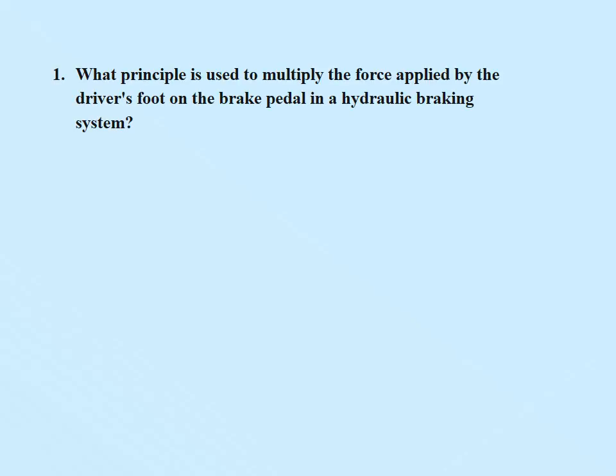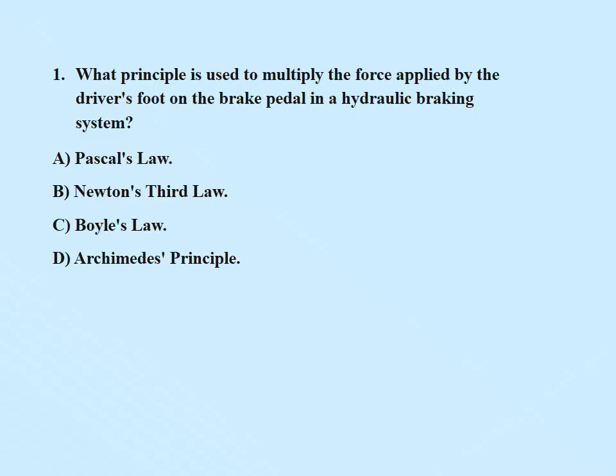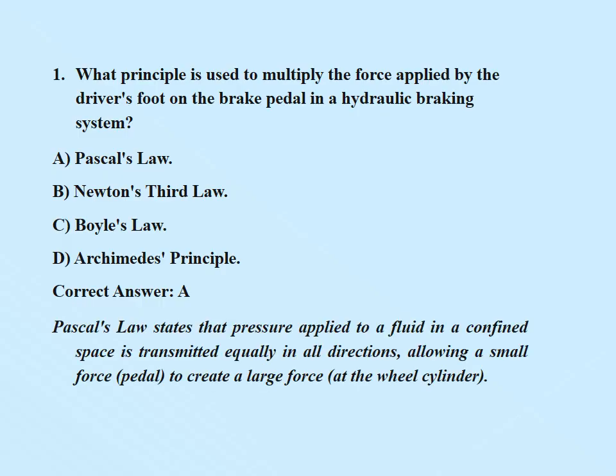What principle is used to multiply the force applied by the driver's foot on the brake pedal in a hydraulic braking system? Options: Pascal's law, Newton's third law, Boyle's law, Archimedes principle. Correct answer is A. Pascal's law. Pascal's law states that pressure applied to a fluid in a confined space is transmitted equally in all directions, allowing a small force at the pedal to create a large force at the wheel cylinder.